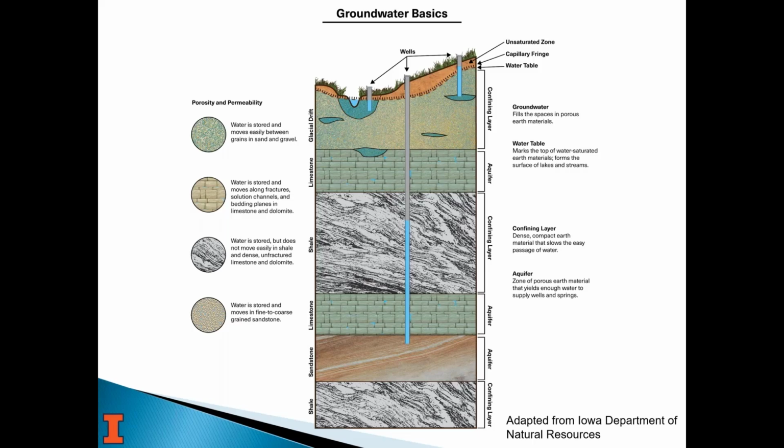So here this well could be getting water from the sandstone near the bottom, the limestone, or the upper limestone. And a lot of times those wells were drilled that way, where they are left open to all those units. And the only time you wouldn't do that is if there was a water quality issue with one or the other. And water quality can vary between those.